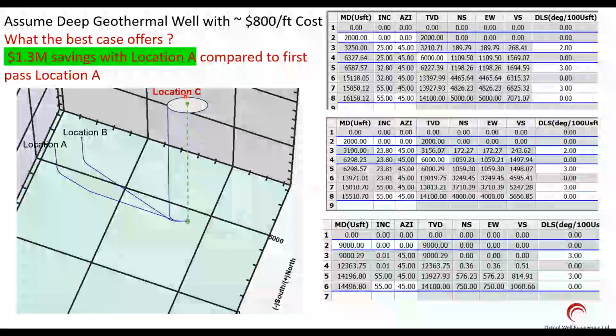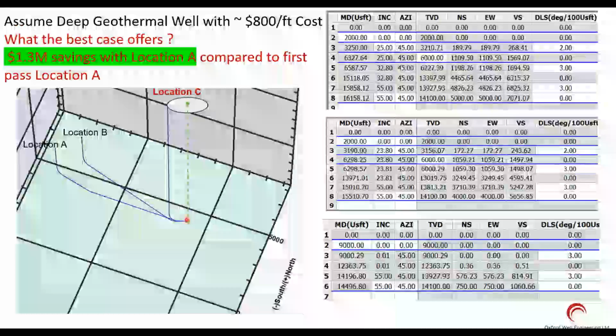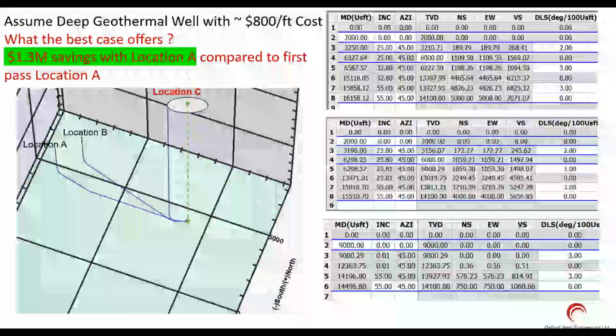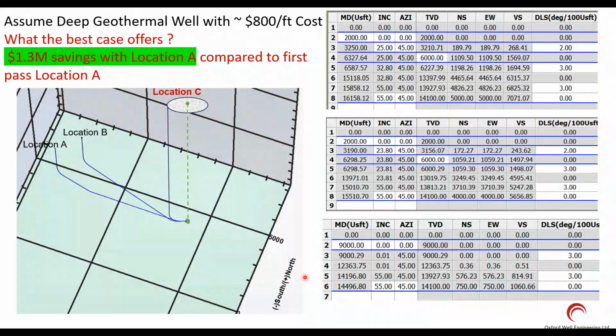The circle you're looking at is telling you that you can drill from anywhere if direction of drilling is not a problem. Suppose the gentleman comes in and says, any azimuthal direction will be okay for me, then I can drill from anywhere around this circle, because I draw the circle around it having this much offset. So you can drill from here and drill like this, coming from another direction. So there's a lot of money that can be saved with these smart interventions.